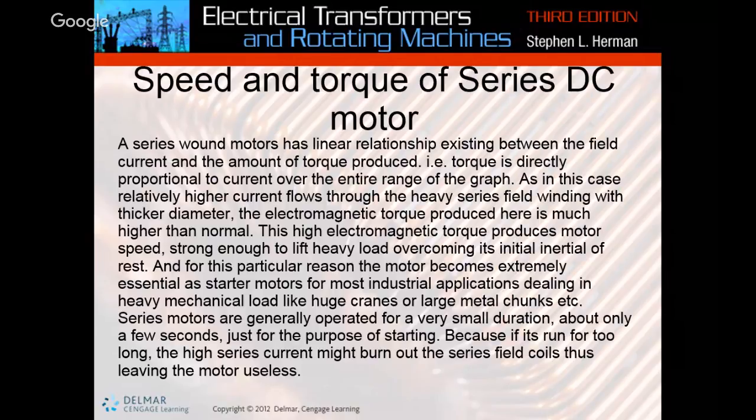But most of the time, all of the DC motors, and to be honest with you, the last time that I even worked on a conveyor, we were getting rid of the DC motors and putting AC motors on, because the technology now has got it to where with variable frequency drives, we can produce an AC motor that gives us the exact same starting torque and all of the benefits of having a DC motor, the speed control, all just right there with having an AC motor. And then with an AC motor, you don't have any maintenance. It just runs. There's no brushes that need changed or anything like that.